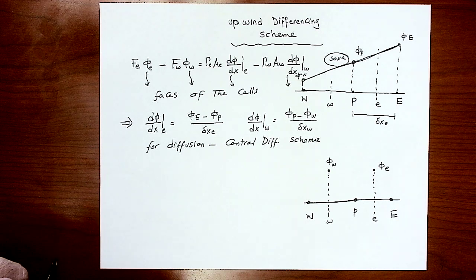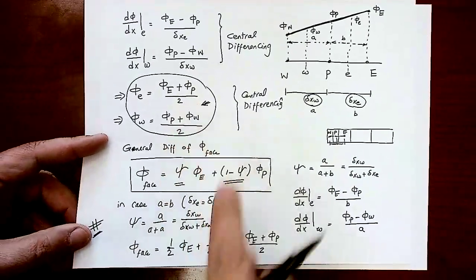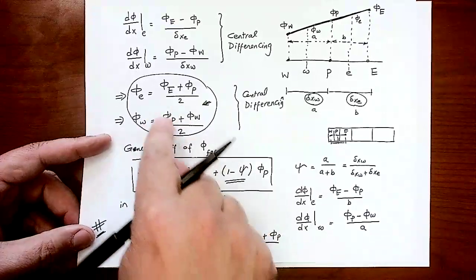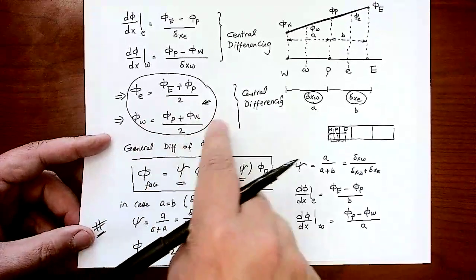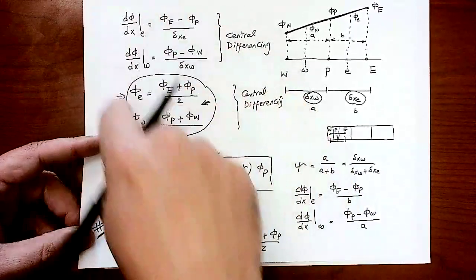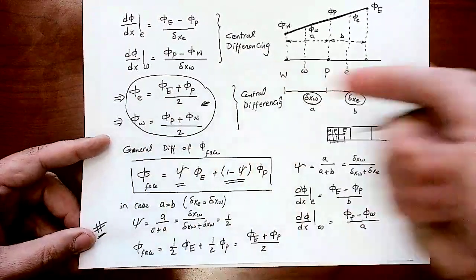Central differencing scheme is taking an average, right? So it doesn't tell you exactly where the flow direction is. Let's recap this. The approximation here is either divided by 2 or there is a different weighting factor. It's an average value, right? Could be 1/3, could be 1/4, whatever it is. But it doesn't tell you what the flow direction is. Is it going this way or coming this way?